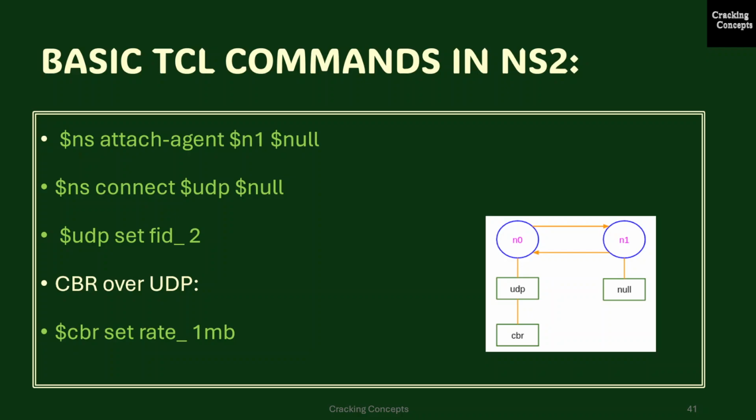Then there is CBR or constant bit rate. It is a term used in telecommunications relating to the quality of service. When referring to codecs, constant bit rate encoding means that the rate at which the codec's output data should be consumed is constant. CBR is useful for streaming multimedia content on limited capacity channels since it is the maximum bit rate that matters, not the average. So CBR would be used to take advantage of all the capacity. CBR would not be the optimal choice for storage as it would not allocate enough data for complex sections while wasting data on simple sections.